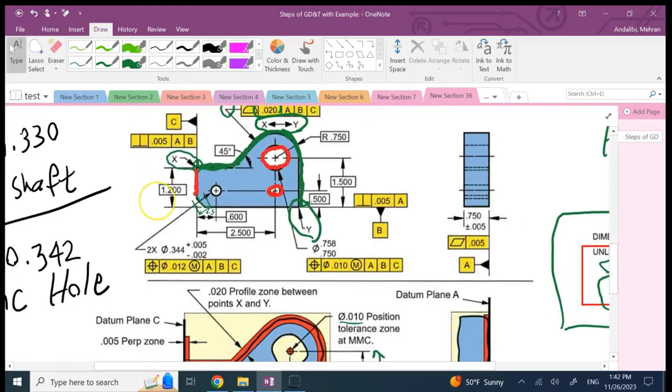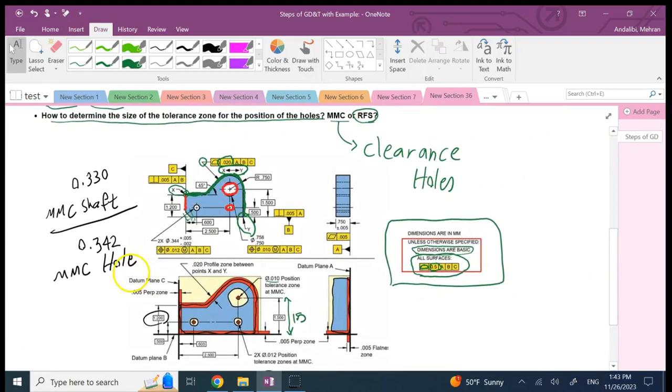That will be for the chamfer or anything else if we miss them. So you always put a general tolerance note next to your GD&T to make sure everything is covered. And this is typically a looser tolerance for the stuff that is not as important yet might not be mentioned in all of these symbols.